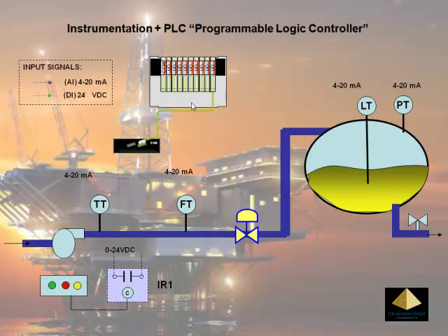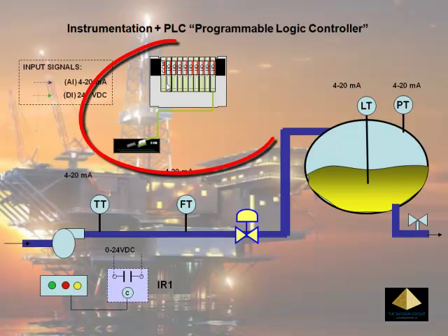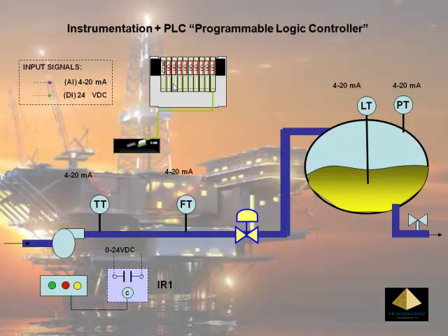There is our programmable logic controller. In short, this is the PLC. It consists of a CPU. It's just like a computer, and it also consists of input-output. There are two types of IOs: the digital and the analog. Now, what we have here are all inputs. The temperature transmitter are actually analog inputs. So this connects to the PLC analog input module.